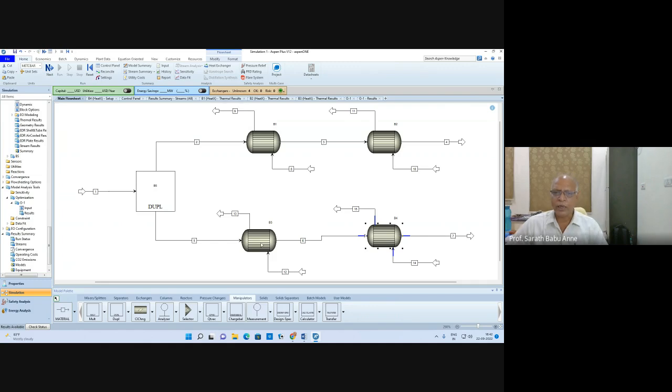So in the same way, if you run the optimization problem on this second option, you will be able to calculate what temperature here will minimize the total area of the two exchangers. So you also try to analyze why the second option is giving you a better performance, in what way this intermediate temperature is influencing the areas. So I will leave it to you to analyze this problem and satisfy yourself with the results of this simulation study. I would like to close down this recording.